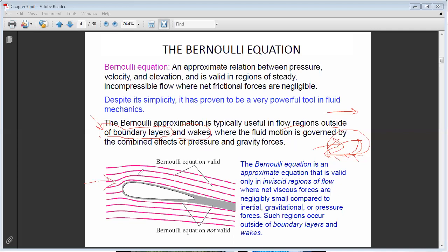If you do visualization of your flow through smoke or through red particles, and you observe the trajectories, you will see that the flow will do a certain separation at this level because of the contact with the airfoil. So the streamlines will go apart here,